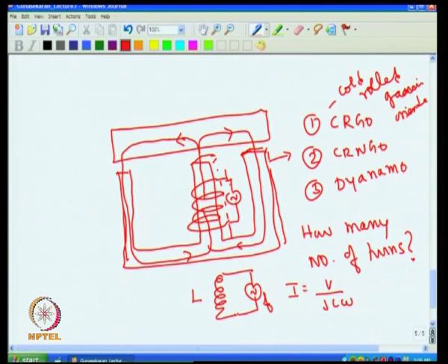But if you continuously increase the current, after some value the magnetic field will not increase. The core cannot take more than a particular amount of flux. For example, if I take a CRGO core, it can accept only a flux density of 1 Tesla. So, we call this the saturation flux density. What is the saturation level?